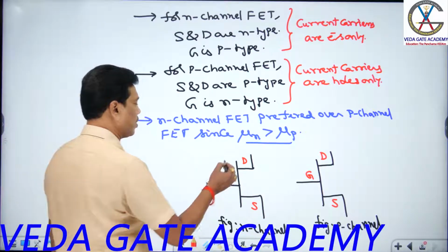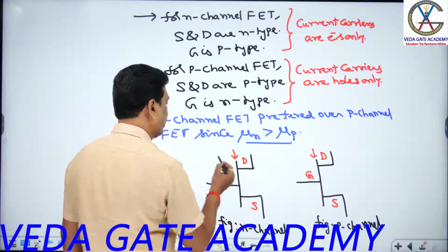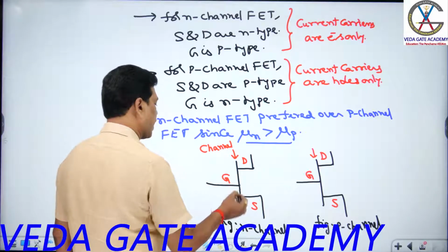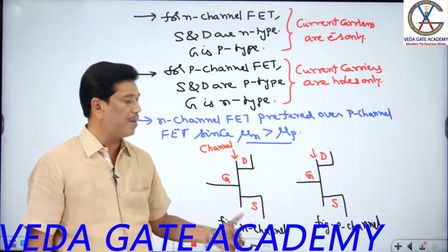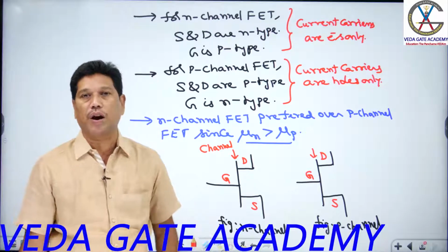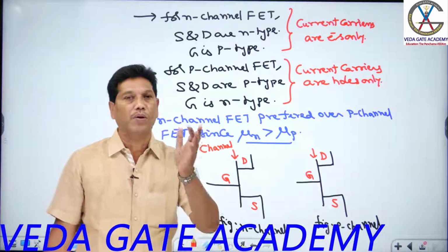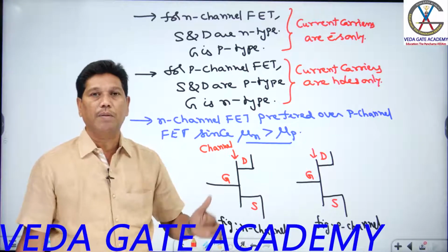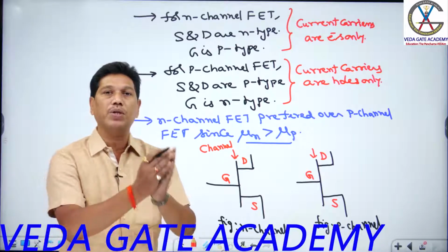And remember, students, this long vertical line connecting the source and the drain is called the channel. So you have a conducting path between source and drain through the channel. In JFET as well as in depletion MOSFET, you can find a conducting path through the channel between source and drain. But in the MOSFET family, enhancement-only MOSFET, according to the construction, there is no conducting channel between source and drain. In the case of enhancement-only MOSFET, you can induce the channel, students.